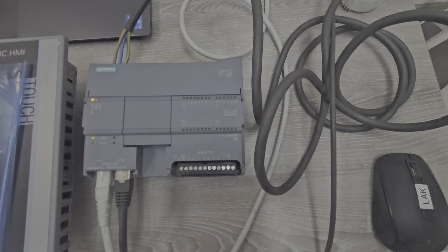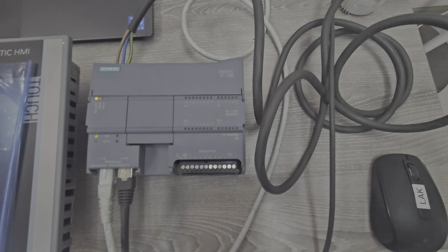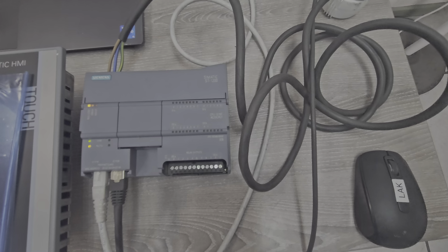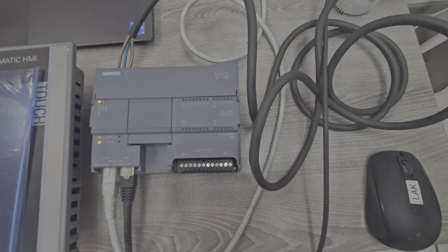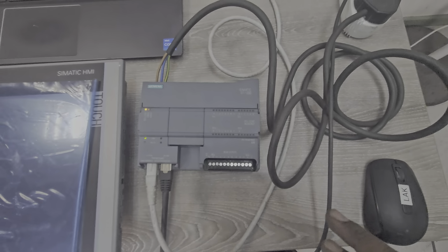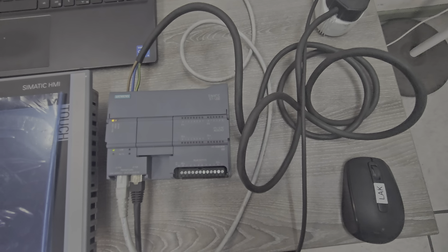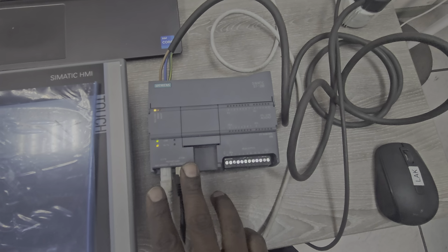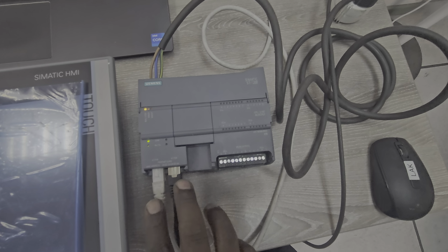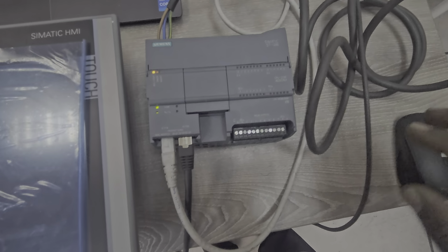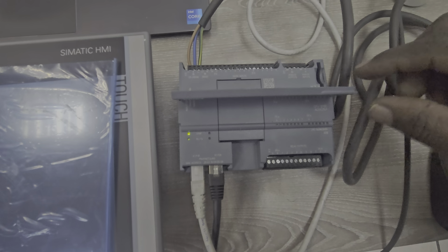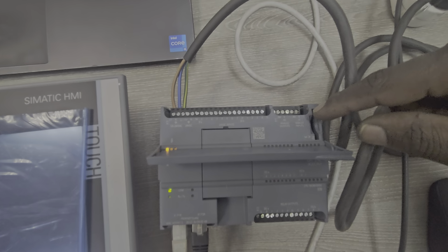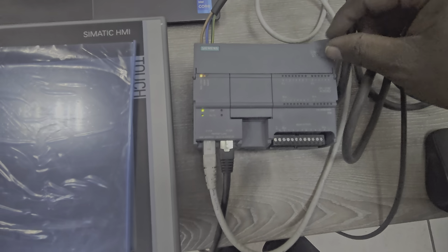Whereas on a modular PLC, you're gonna get a digital input card, digital output card, CPU, communication card, analog input card, analog output card as separate units. But on this one, the CPU is built onto this one. The comms CP card, which is the communication, is also here. The digital inputs, you can connect your digital inputs here, and your analog outputs and your analog inputs. So everything is built onto one.